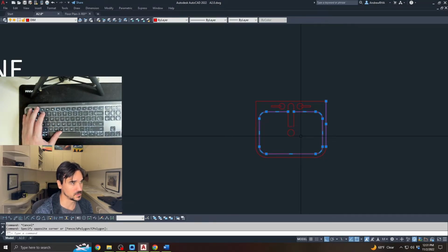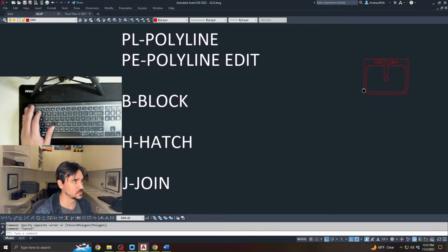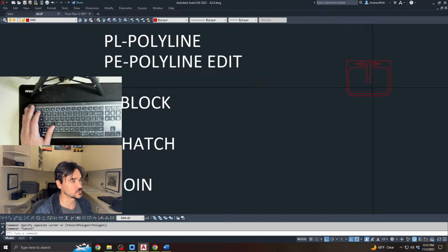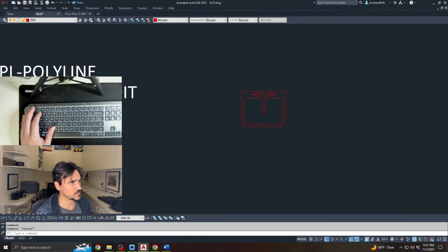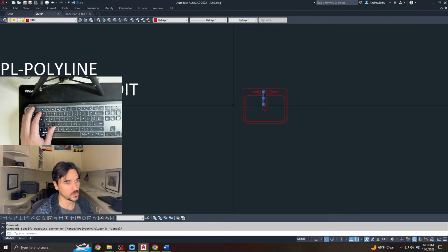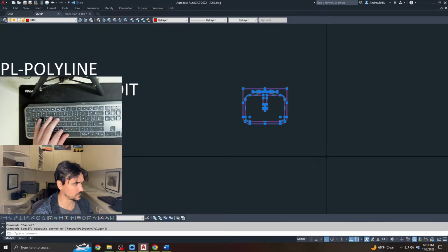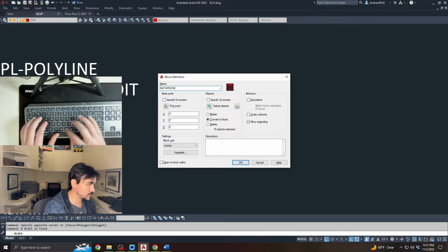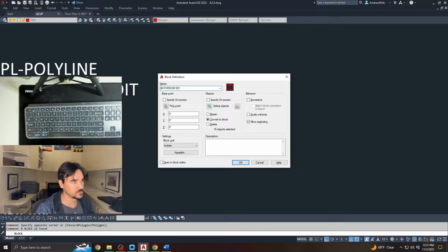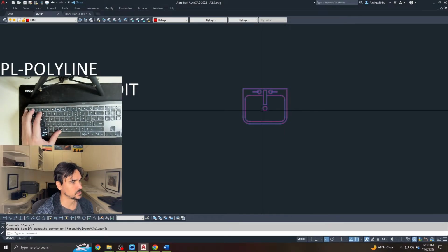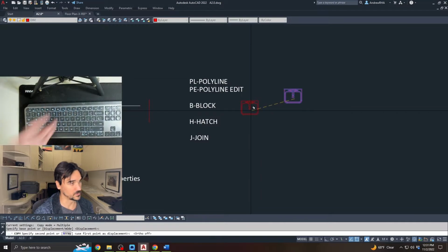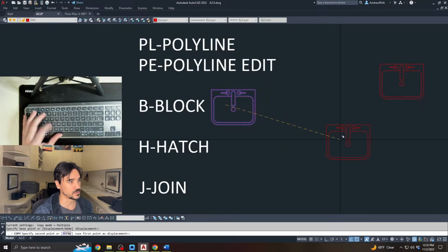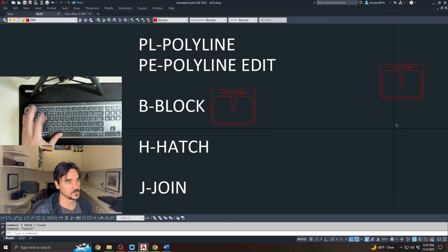Now the problem with this is all of these components are all individual components. And they are all polylines just for keeping all of these lines kind of more editable. This one was exploded, so it's not, but I have this block command here. So if I want to change this sink to one object, I would just select all of the components, hit B, enter, and I'll name it bathroom sink. Bathroom sink 001. Hit OK. Now this sink, it didn't take me very long to draft, is a block, and I can copy it and put it in any bathroom I need to. Okay.